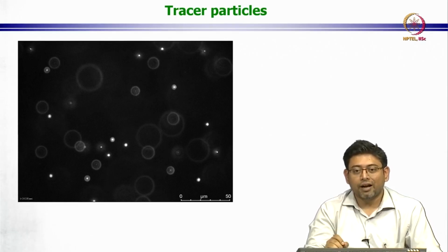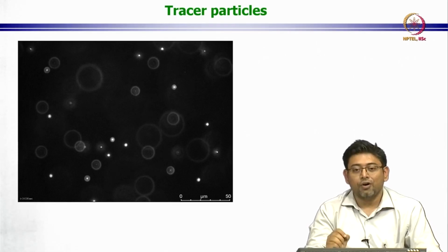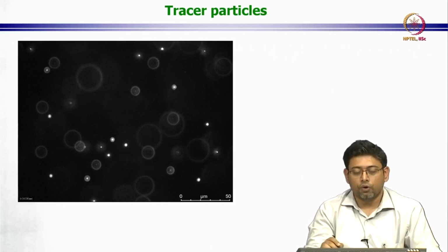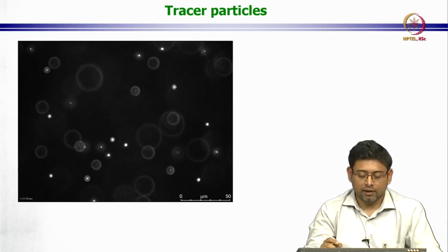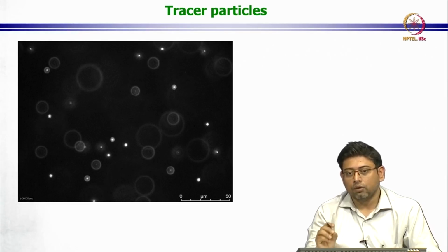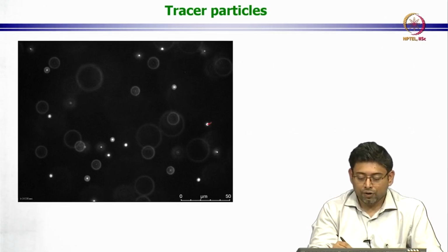Something that is not interacting with light enough, you have to visualize and quantify the flow of that. So how do you do that? You cannot visualize flow easily in such a case. There are some techniques like Schlieren, which we will go into again, which allow us to look at flow patterns qualitatively in gases and use some of the weak interaction to visualize. But if you want very strong quantitative data, like in particle image velocimetry, where we want the velocity field, it becomes very, very difficult. And that is where we have to use particles like this, and this becomes our tracer particles.